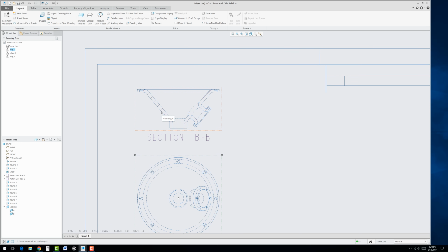Okay, now a couple other things. You could actually double click on the X hatch or the cross hatch. And over here on the right you have the ability to adjust the angle, the spacing, the offset, line style. So let's say I go to spacing. Let's go to half, and you'll see it will reduce it actually by half, the distance between each line. I'm going to hit done. Okay, so that's how you could adjust your crosshatch.